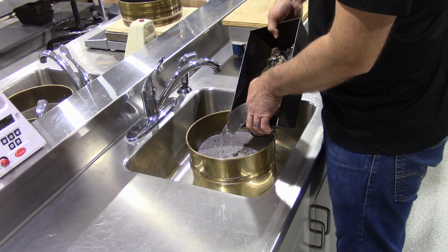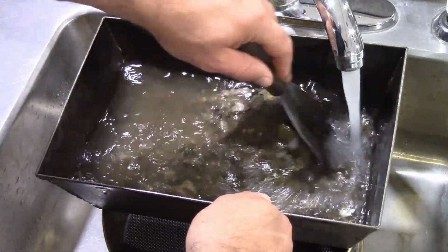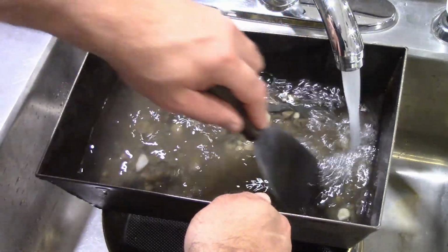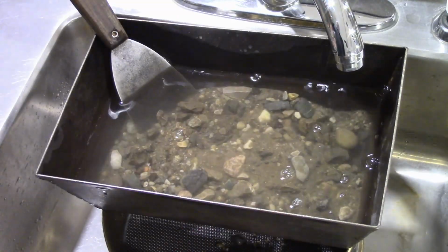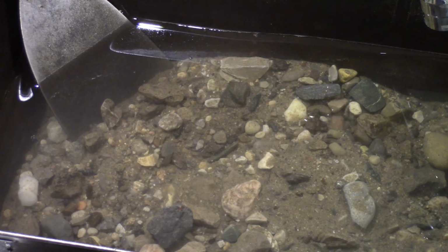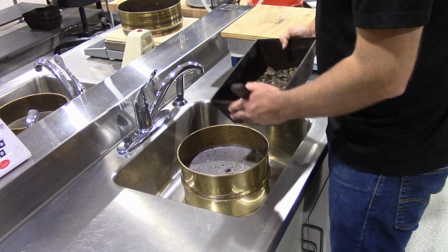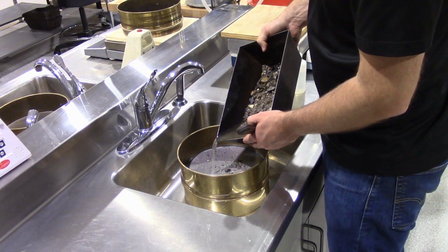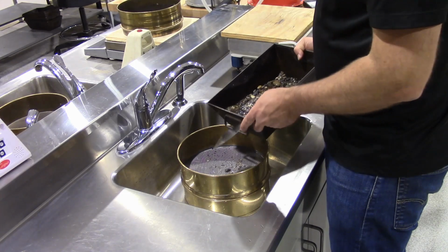Make sure nothing drips outside the sieve. A drop here or there may seem inconsequential, but it all adds up. Use care, accuracy, and precision to ensure accurate results. When the water becomes very clear, so that no stone particles appear clouded after 10 seconds, the sample is considered washed. Use due diligence to make sure that no pockets of clay are present in the bottom corners of the container. This is another common mistake made by new technicians.